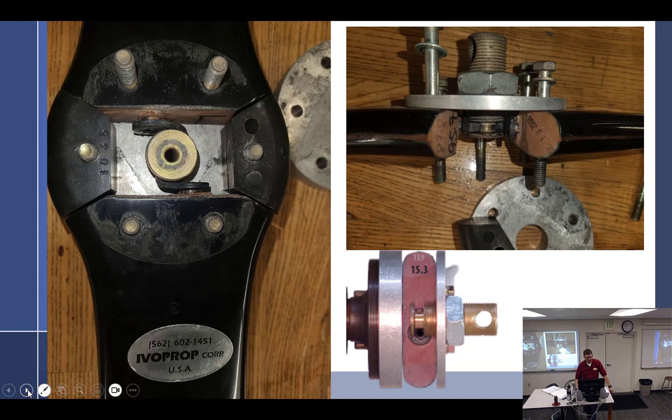Yeah. They're carbon fiber. So in regards to that, let's say you have an issue with one blade on your prop, can you switch it out, or do they have to all be together like that? Yeah. So you're flying along, got your 3-blade prop, and you actually nick one of the blades. The other 2 are fine. Just take out the one that's bad, throw it away, make it 3 into 2, and go flying some more.